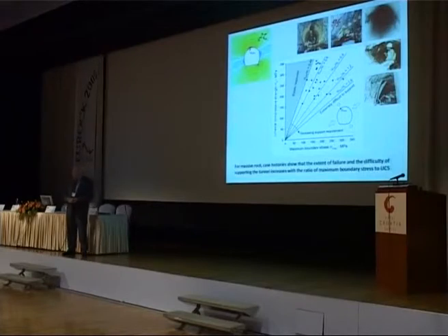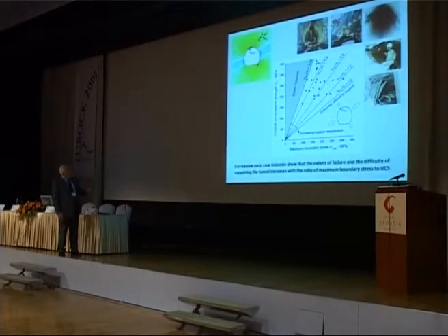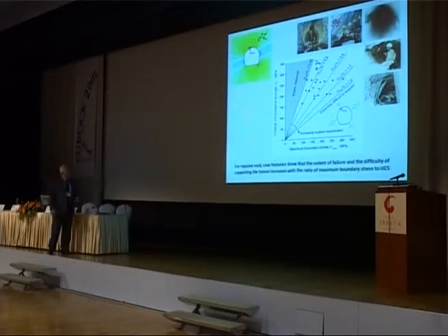Starting at the massive hard rock end, we know from experience that if you look at the stresses around an opening, and I'm just taking an elastic example here, you calculate the maximum principal stress on the boundary, assuming that you know the in situ stress field, which, as John has pointed out, you don't always do. Failure starts at about 0.45 of the uniaxial compressive strength as determined in the laboratory.